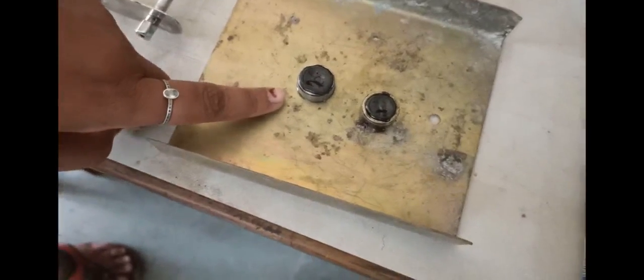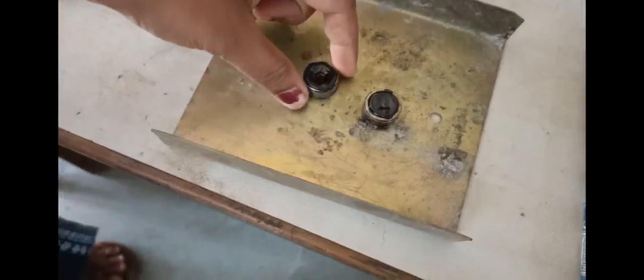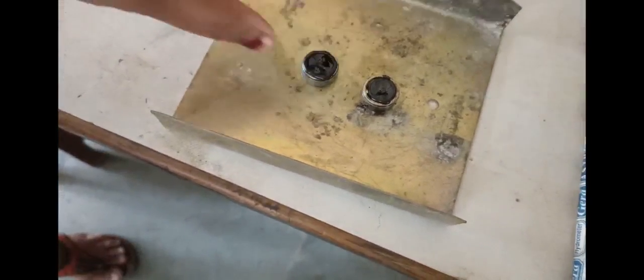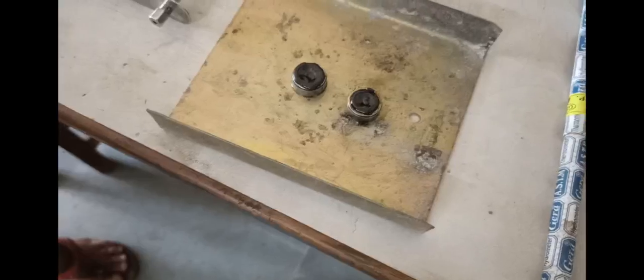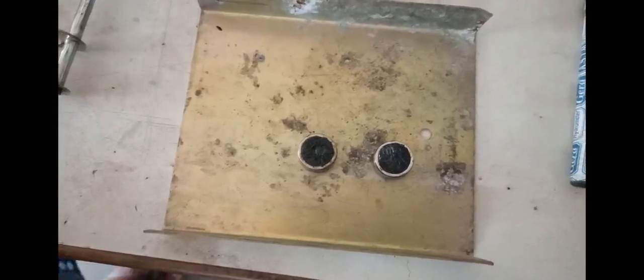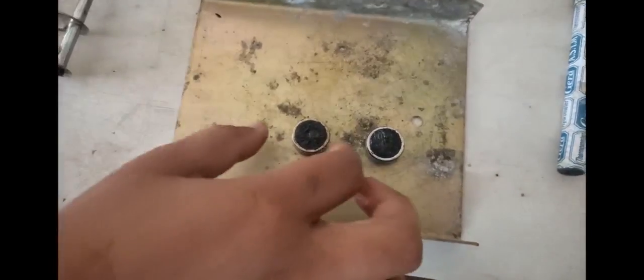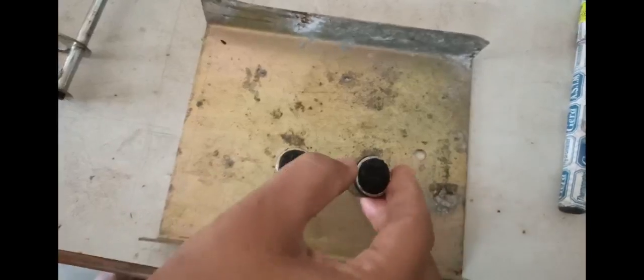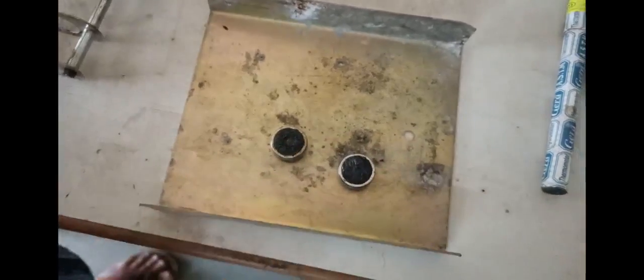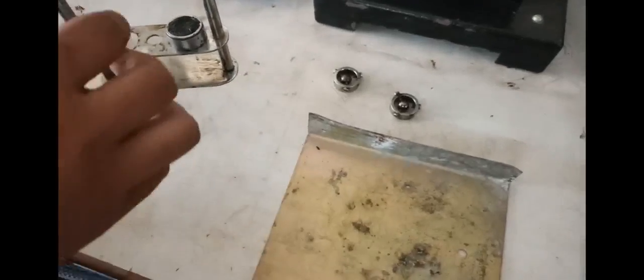After pouring bitumen in the ring, you can see there is extra bitumen. We have to remove it after 30 minutes. We have to keep this bitumen at room temperature for 30 minutes. After 30 minutes, we have to remove the extra bitumen. You can see after 30 minutes, I have cut the extra bitumen. After cutting the extra bitumen from both the rings, we have to place this ring with bitumen in this apparatus like this.